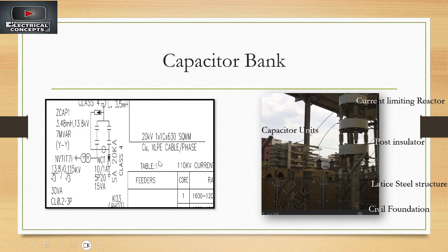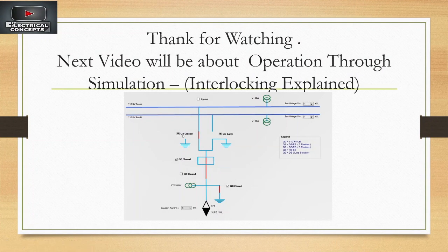So let us conclude here. I would like to give some tips for the project managers or project team, that while you are designing the MV switchgear, you should get the base design at an early stage and share it with the designer to generate the electrical layout. You can do it at an early stage as it will open a work front for you to start the civil works. This coordination is very important: the switchgear hall should be designed according to the switchgear itself, especially the openings under the panels, which are the cutouts in the floor slab. So cutouts in the slab should be done at one time and should be 100% accurate.